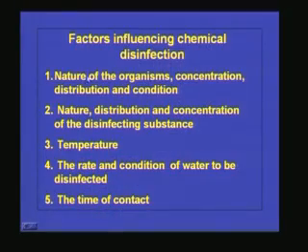That is one reason. Another one is, yeast and others will form cysts. These cysts are highly resistant to these chemicals. So, if the microorganisms are of cyst-forming nature, then naturally they will not be destroyed by any of these chemicals. And if you have a very high concentration of microorganisms, then also it is very difficult to achieve 100% disinfection unless we add a very high dose of disinfectant. So, the nature, concentration and distribution of microorganisms are very, very important.